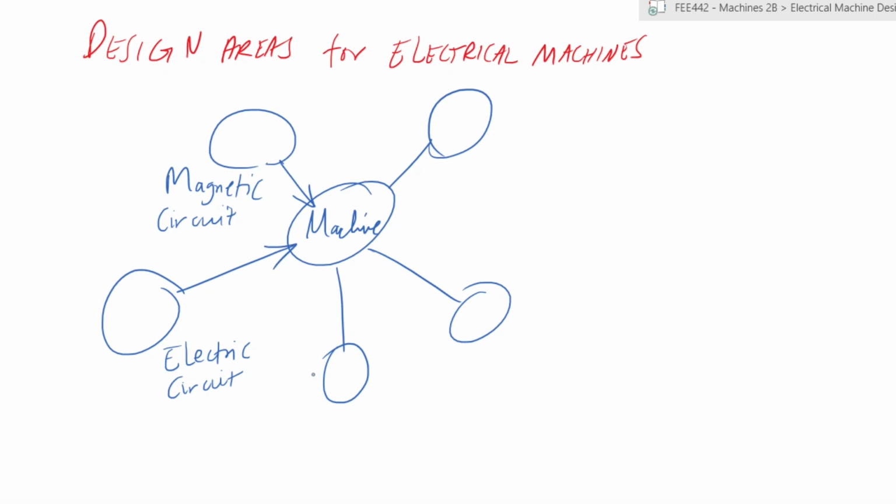So generally, your magnetic circuit would be the frame or the yoke or the mountings on which the windings must be put that allow a magnetic field to be set up within them. Usually these are made of ferrous materials or materials that have a low reluctance and enable the magnetic field that is required to interact with the electrical currents to be set up within those materials.